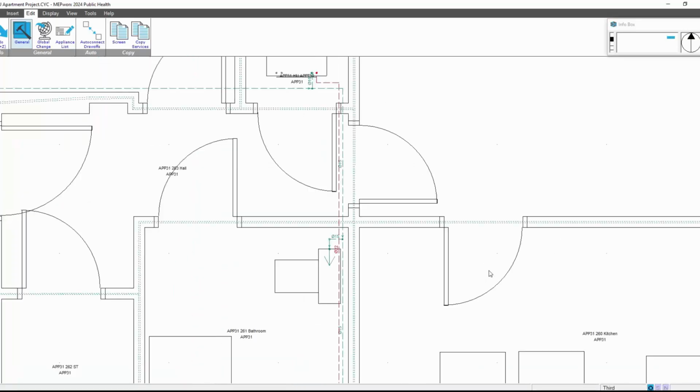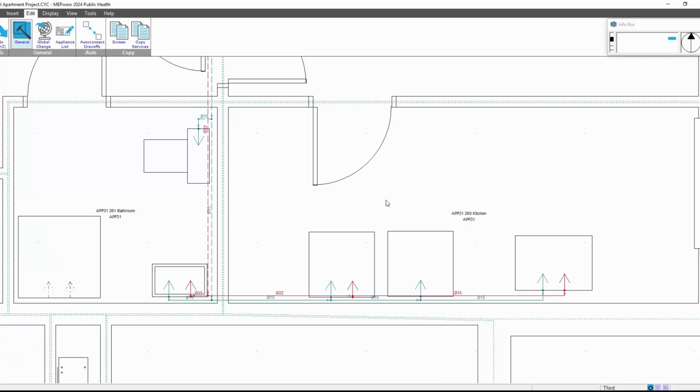Irrespective of the number of appliances you have, it strictly looks at the tables from the codes of practice. So no matter how many appliances you have, it'll just be based on the number of bathrooms or single appliance or number of bedrooms. So it uses the codes of practice to determine the diversified loads to the heat interface unit on the landlord supply pipework setup.